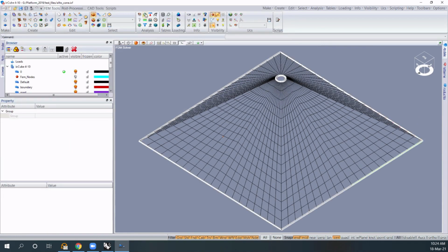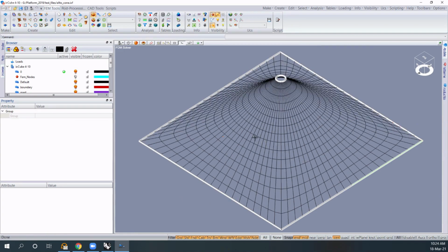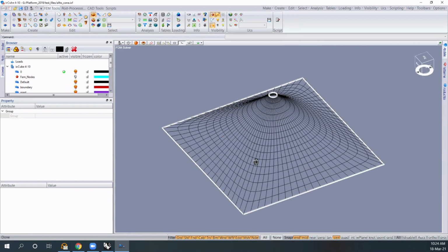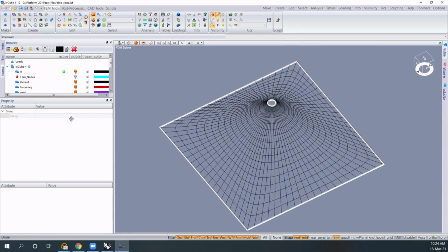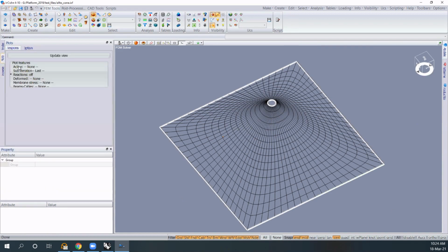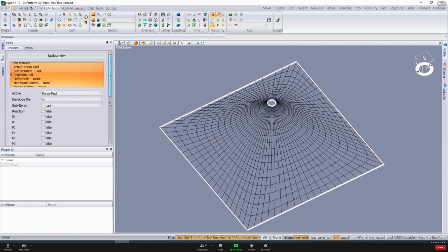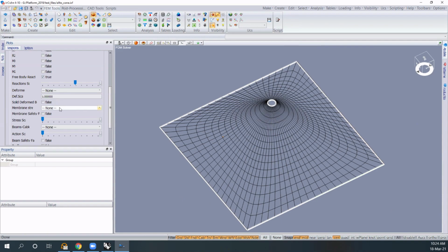We have here two form finders, a form find stiff and a form finder. You can use the form find stiff when you do not want to take care of the steel. So you just run the form find stiff and you see that the software has relaxed the shape into a conical shape, quite ugly conical shape. Before going to change the shape, let's give a look at the stresses in the shape. We go into the response here. We choose response after the form finding step. And since we're using the force density method, I want to give a look at the principal stresses in the membrane.